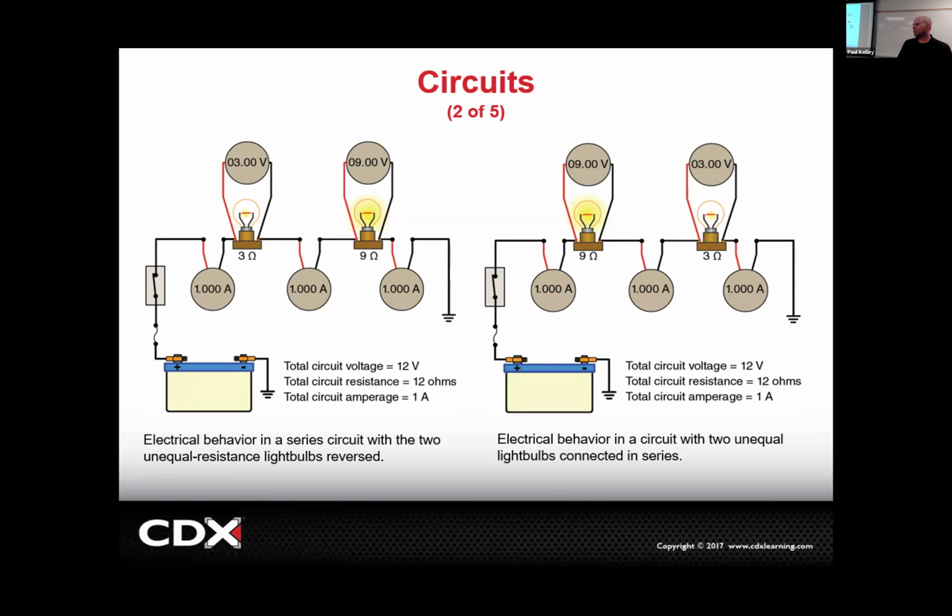See, remember in the beginning I told you if there's a dim bulb, I already diagnosed in my mind it's got unwanted resistance somewhere, right? In this case, it has unwanted resistance because it has a second bulb added in, and that'd be very easy to see because it's glowing in your face. But if it's corrosion, it doesn't glow and shine in your face. You're just like, why is the bulb dim? I don't know. And then you could measure and be like, why is the bulb only consuming 3 volts? And I'd say, because there's like 9 ohms of corrosion in the circuit that's consuming 9 volts somewhere, but I don't know where. We got to measure that.